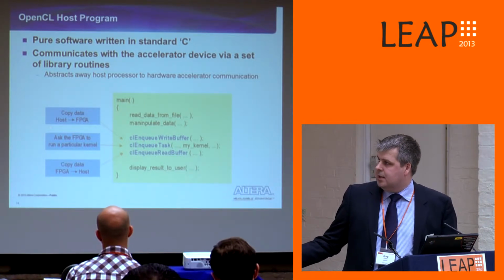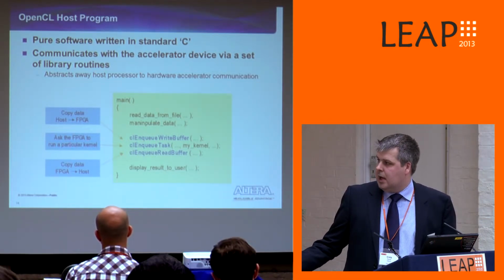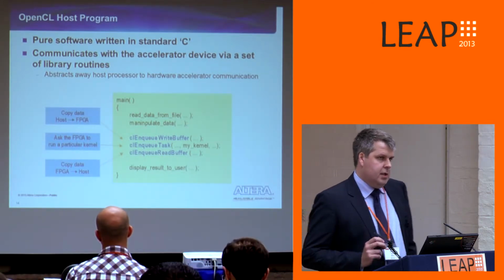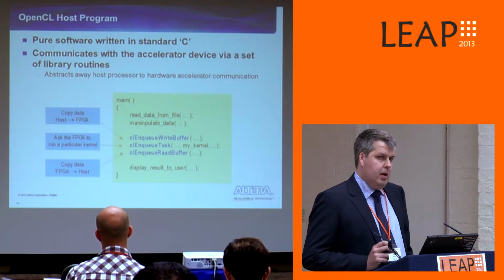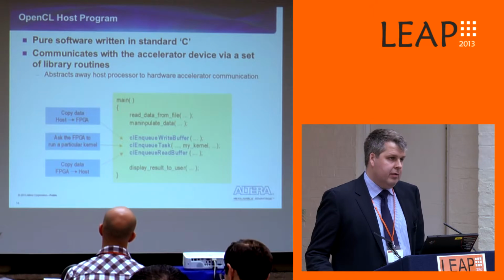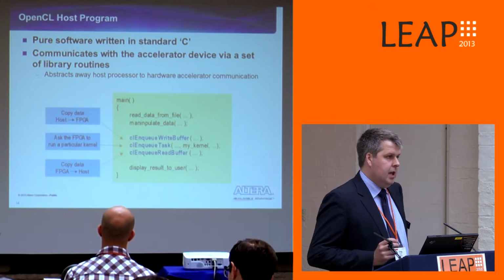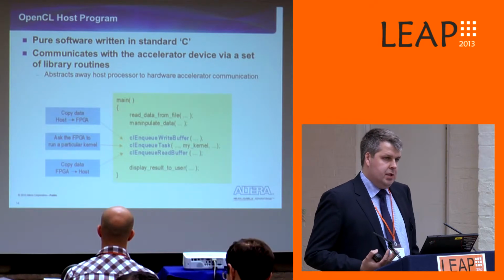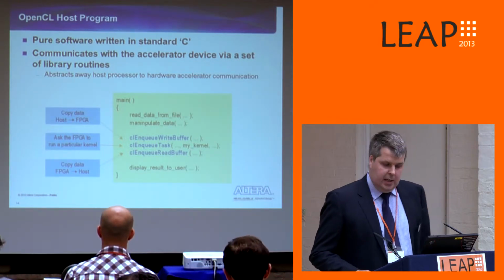All we're going to use is copy data from the host to the FPGA, run it, and then copy that back. Now that doesn't necessarily have to be by PCI Express. It can be by any interface we would like moving forward, but currently our implementation is using PCI Express as the interface. And that can be up to PCI Express Gen 3 by 8 lane interfaces.